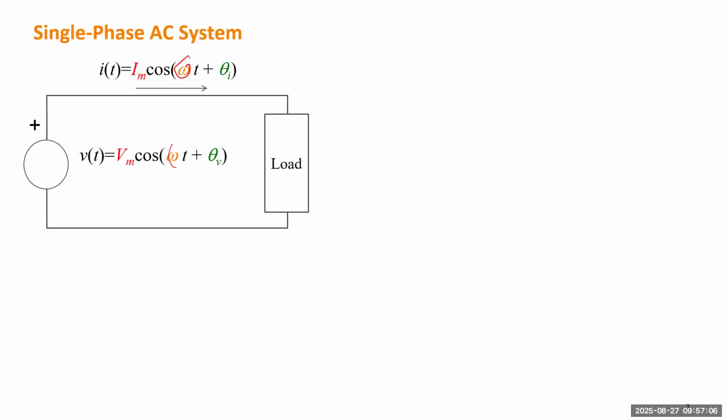But in reality, if you measure the voltage and current, sometimes it will become rectangular or triangular. Which means the current is not just a single component. There will be some other components, like the third harmonic, 3 times omega plus some angle, right? There will be the fifth harmonic, the seventh harmonic, or maybe odd or even numbers. There are many such items.